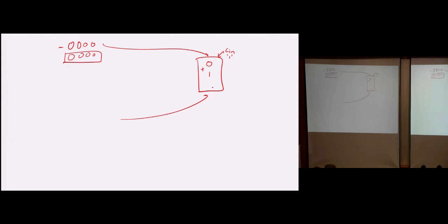If I ask you to give me a 2's complement, what would you have done? You would have flipped and added 1, right? It will still be all zero. That's what the hardware is doing. So you flip and add 1, correct? So what's the output here? Zero, carry over 1. So this carry in becomes 1.